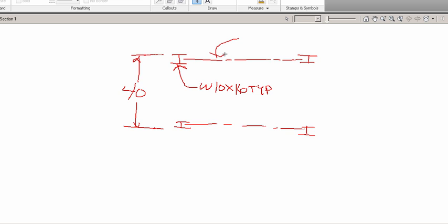And then we've got the beam. So let's just say this is a W16 by, I don't know, we'll just make it up, W16 by 30. Okay. That's how it would show up on a set of plans. And steel fabrication is kind of how it goes. The plans show this bit of information, and there's a lot of other stuff that gets thrown in with it that we can talk about connections a little bit later. But that's a W-beam. Very, very important for you to understand getting started on how this looks, and we'll take a look at another one here in a second.